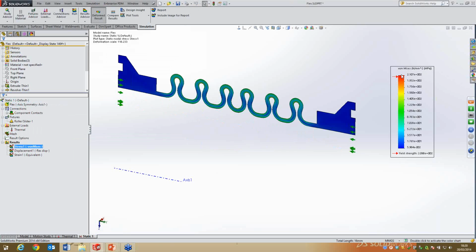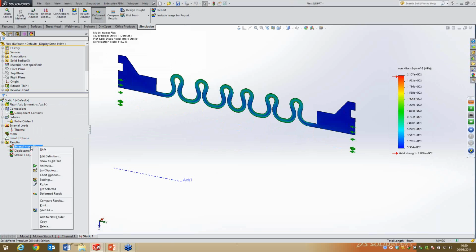With that amount of thermal loading, it's very close to yield. All right, it doesn't necessarily mean it's going to be a bad thing. You may find after it's been through a few heat cycles, these stresses would come down, but it's definitely going to displace it a certain amount.